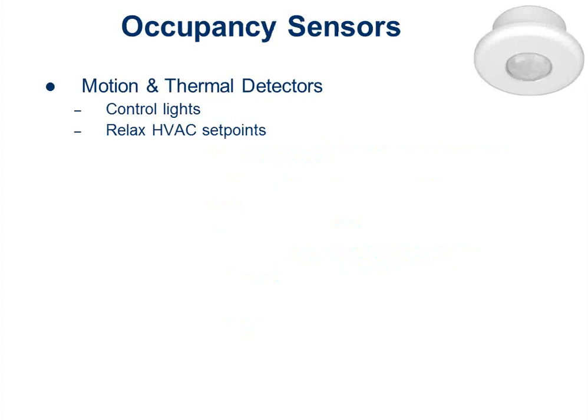There are a few other ways you can do it. You don't have to do it with CO2 sensors. You can track whether people are there or not other ways. One common way is with occupancy sensors. This is really kind of a go or no-go thing. It works well for school classrooms. Either the kids are in the room, and I'm going to ventilate for 35 kids, or they're not in the room, I'm going to ventilate for nobody. Yeah, it's true that you may have 28 one day instead of 35, and you don't get to capture that with the occupancy sensor, but you still get kind of close. So if you want to do it with occupancy sensors, it does work in certain applications, like a classroom.